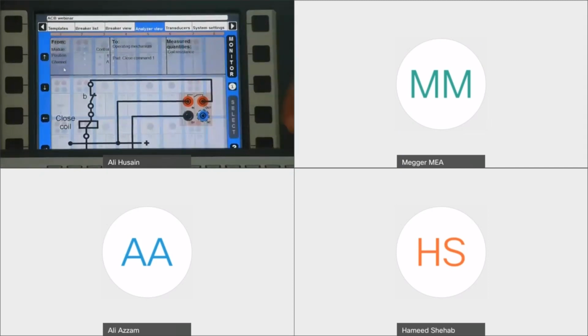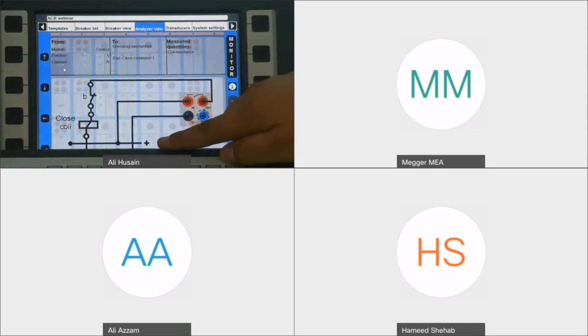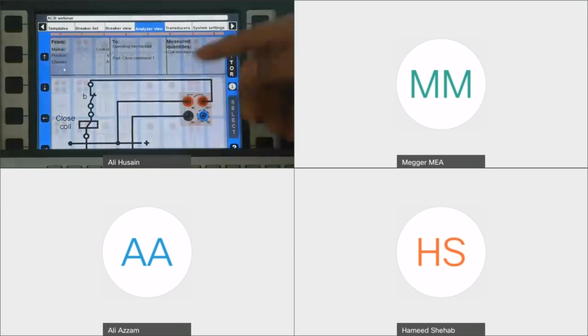And so here it's showing me that I have, I would say, four connections in this module. I have in, I have out, and I have 0 volt. Basically the in and out show that I have to connect to my DC supply. So this is what I did. I connected to positive and negative of my DC supply. Unfortunately, you cannot see the negative. It is down below here, blocked by this keyboard here.